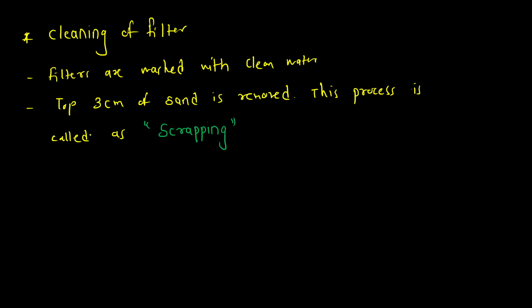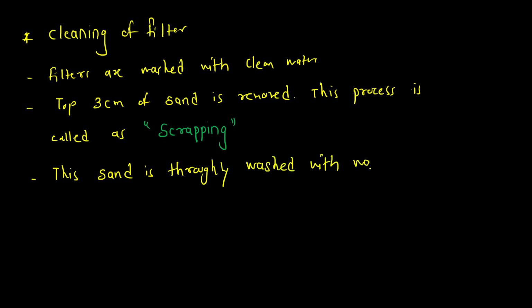The topmost 3 centimeter of sand which is removed, this sand is thoroughly washed with water. We'll wash this sand with water, then we'll dry this, and then we'll reuse it again.